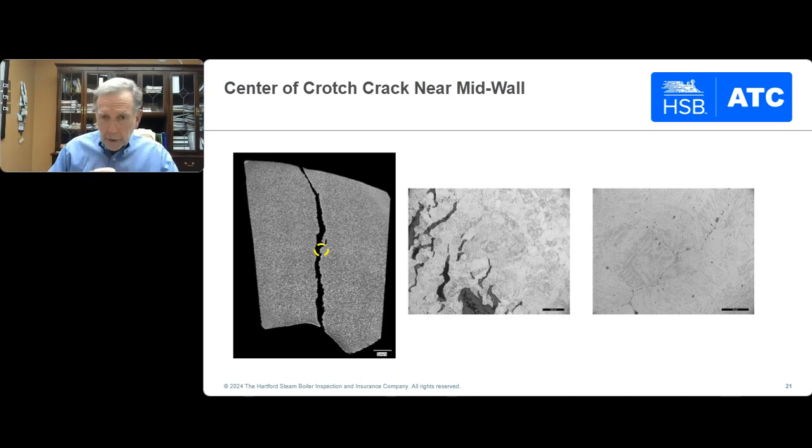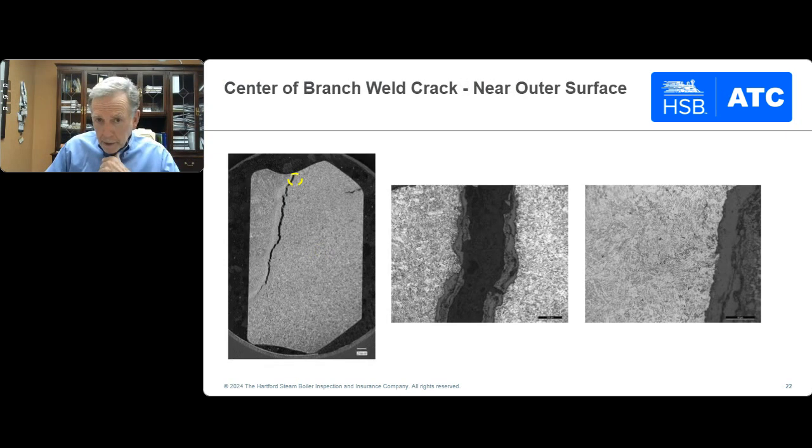And then Jay is going to talk a little bit more about exactly why that's occurring, but we did want to demonstrate just the nature of the damage. This is showing the damage at the girth welds. You can see in this case that the cracking has initiated at the OD surface and is propagating along the outer edge of the heat affected zone in the grade in this particular material, the so-called type 4 region.